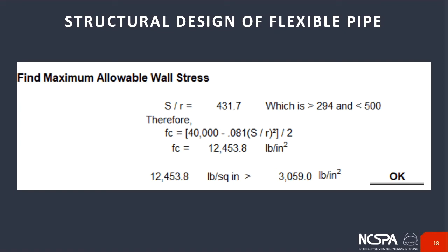as pipes become more slender, or larger structures with smaller radius of gyration available, pipes will fail in different ways. If you remember back to the old Euler buckling formulas, buckling was always based on an L over R ratio, which was called the slenderness ratio, and it fell into three camps.